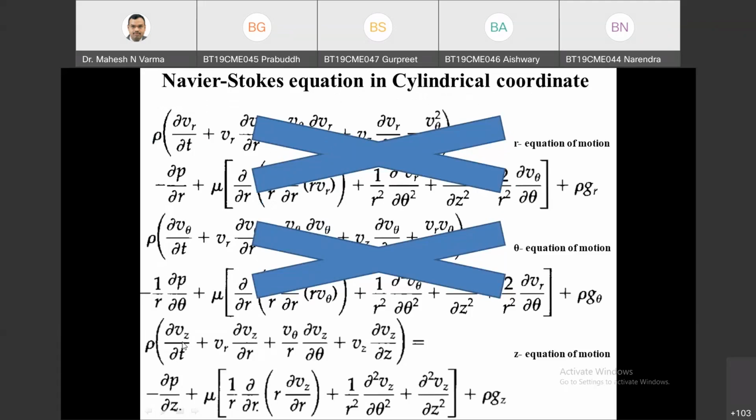Excuse me, sir. Tell me. Sir, in the different forms of the equation, we have 5 equations. Why are we using the second one? Sir, we should use the fourth one. Yeah, that you can do, because our flow is non-accelerating. We have constant velocity in the Z direction. So anyway, if you use the second also, you will get the same equation ultimately.